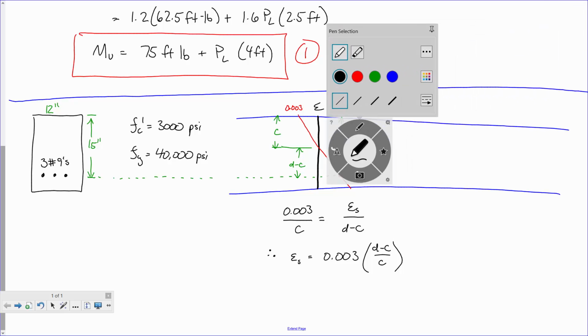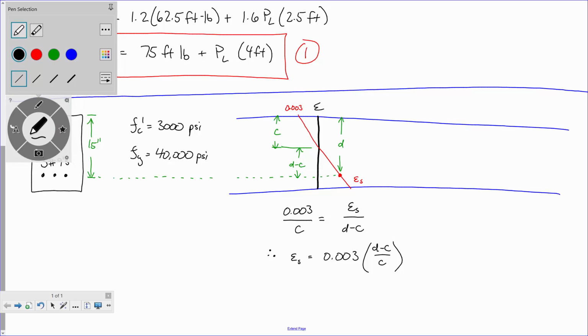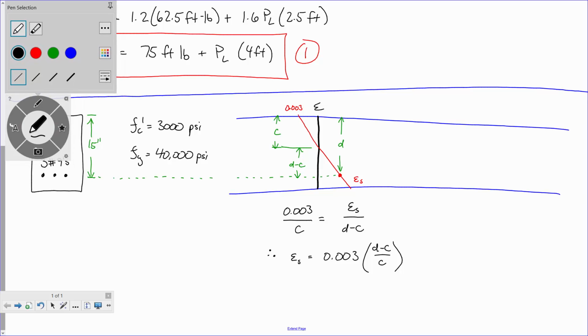Let me move my little pen box thing over there. All right. Now, this is bringing it back, isn't it? Y'all remember this? Now this is going to be my stress profile. All right. Now remember, we're dealing with concrete, and concrete is a material that's very, very strong in compression and very, very weak in tension. So in the tensile region, there is no resistance from concrete at all.